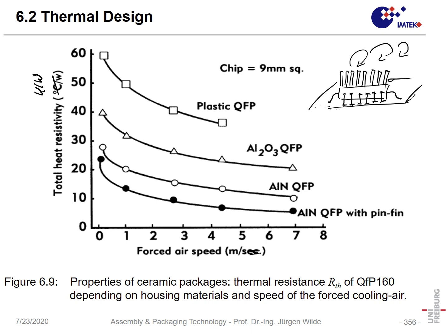If we take aluminum oxide, the thermal resistance generally is lower. Why is it so? The aluminum oxide will distribute the heat better in the device, and so in that way, generally, the area which can be efficiently cooled will be larger.